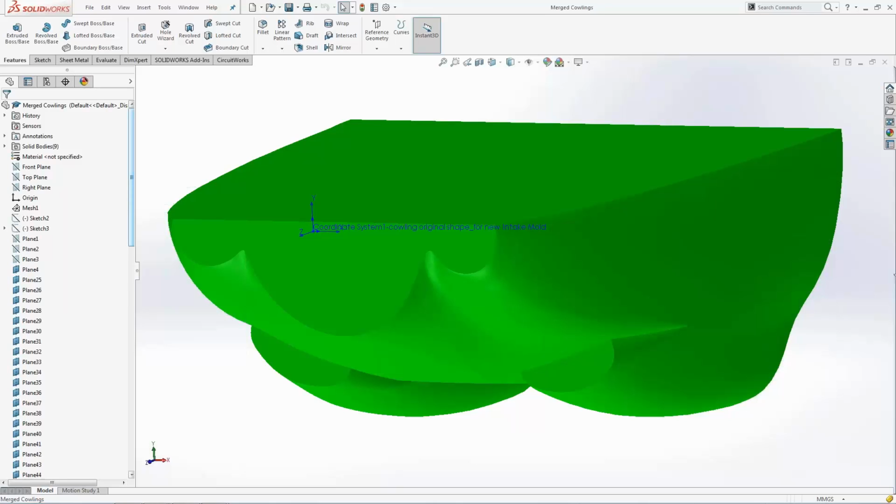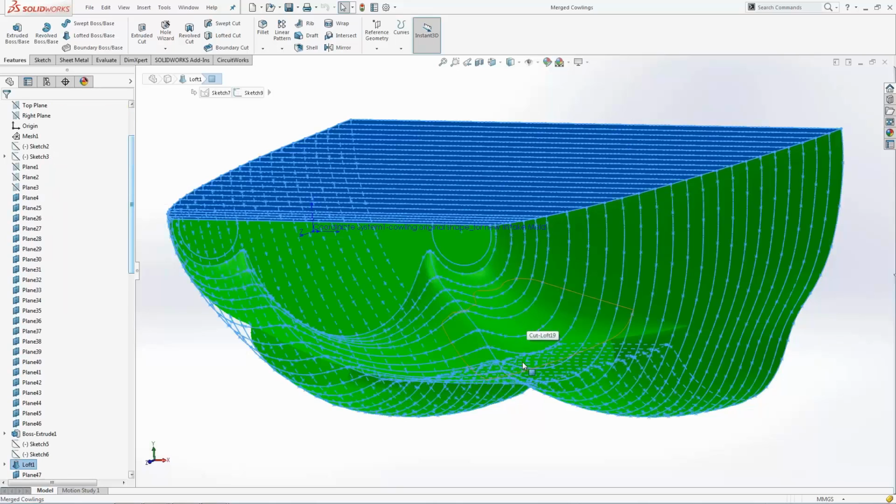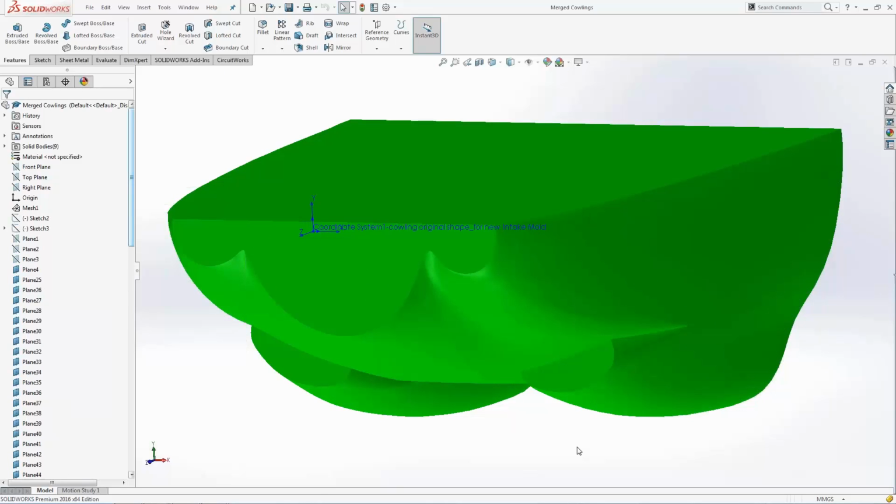And I don't know how familiar you are with manufacturing. This does not turn out to be a solid. It's got a wall thickness to it, so take that with a grain of salt. We did cut some of these holes out after the fact for the spinner and the air intakes and things. But really, this was the item we wanted. And now I needed to get that tooling. So this is where we use the multi-body Boolean operation that I mentioned earlier.